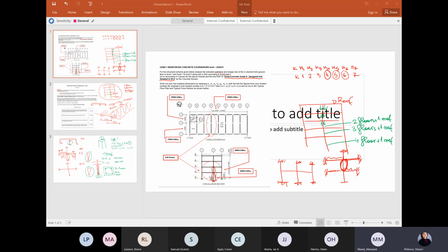And for the self-load of the beams, T-beams, we can pick any dimensions that we want within the right limits. I think in the guide, because this is the example that they solve in the guide, but obviously it's slightly different because of the dimensions and the flooring system, they start with 250 by 450 for the beams, I think. So perhaps that would be a good start.